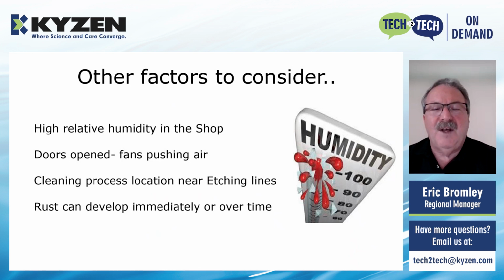And as we know, rust can develop immediately or over time. As I mentioned, the parts come out of the process, and if they're very hot, the water can flash off, and that can cause rust before you can put some corrosion protection on it.